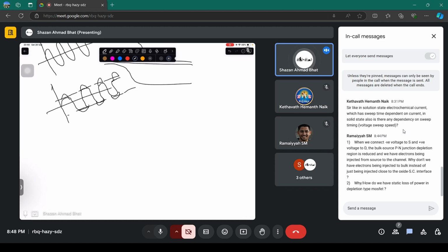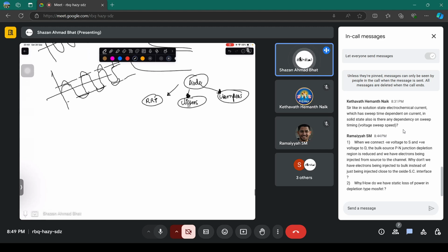At what rate you are going to sweep the gate to source voltage, or in case the voltage in the diode. That's why whenever you study diode circuits, you study about clippers, you study about clampers; these are analog electronics topics. You study about when the voltage will be clipped and other things. You also study about reverse recovery times of a diode: what happens when the charges have to move back, whether the current is able to follow or not.